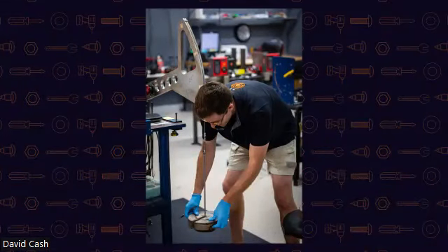But we get the values from the resistance that happens through the actual calibration process of the torque analyzer. And we use that same torque formula of length times force. And in this image, we have weights at a certain poundage that is connected to a segment arm that is connected to the actual sensor.